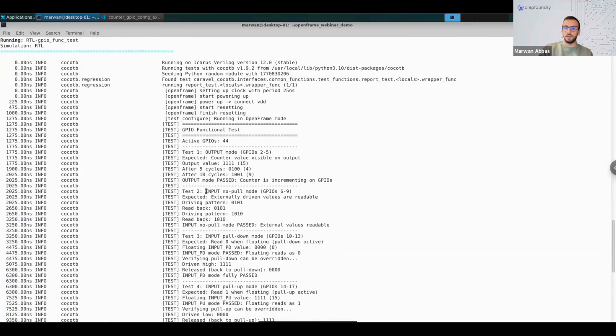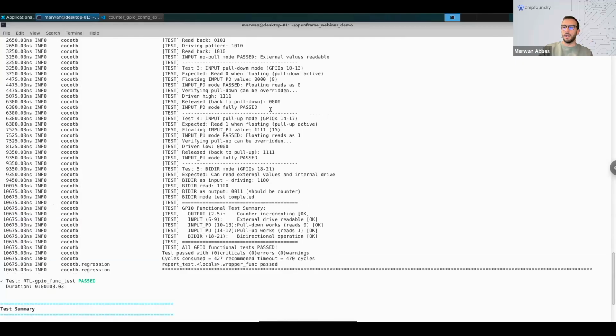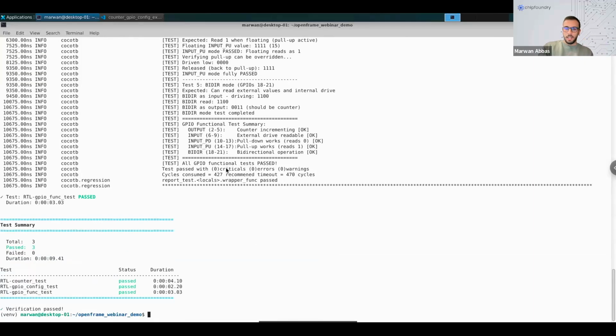And we did clean up the output from CocoTB, so it actually looks better and is easier for you to debug and understand how the tests are working. And of course, a lot of that is having logging inside the test itself, because we're using Python, so we can add logging.